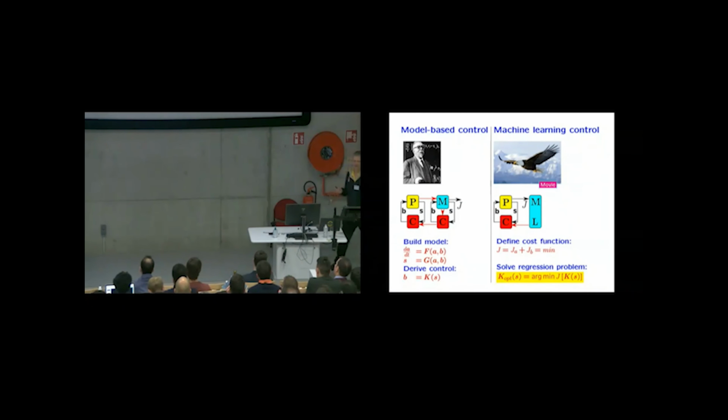So first, I will show you a case, the cylinder wake, of course, where we have this data. And the task is as follows. We cannot build the controller based on the Navier-Stokes equation, because if anything is larger than 10-dimensional, then the control methods typically blow up or become very difficult. So we would like to have a low-dimensional model of our original plant. Here you see the plant. B is our actuation signal, and S is our sensor signal. So it's sensor-based feedback control.